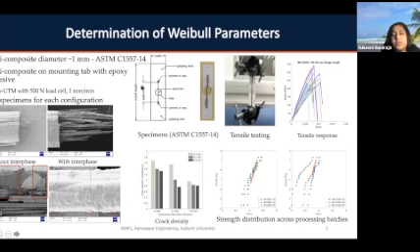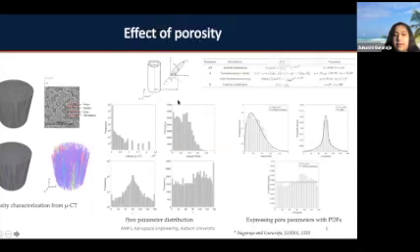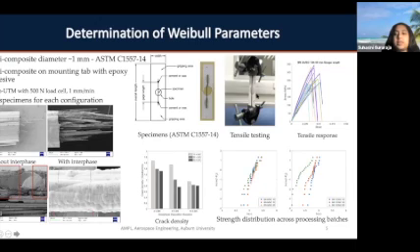So that brings in the different kinds of tests that we have done to understand the tensile response of these materials. One of the reasons you have boron nitride as an interface is, as you can see here, the presence of a weak interface helps in improving the performance of your composite. Typically these carbon silicon carbide materials are extremely brittle. If you do not have an interface, the material just cracks very easily and shows brittle fracture. But in the presence of an interface, you have a lot of fiber matrix debonding, which gives you a quasi-ductile behavior in the tensile response.